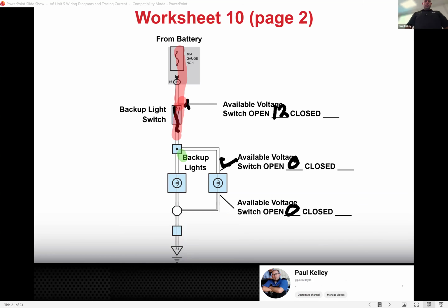It's connected. It should go to the splice, then to the load. It should stop at the load and not go through the load. So now we should have red going to the load. Now we should have green coming up from the ground and going into the load. It should always change from red to green at the loads. Make sense? That's another way to visualize that.